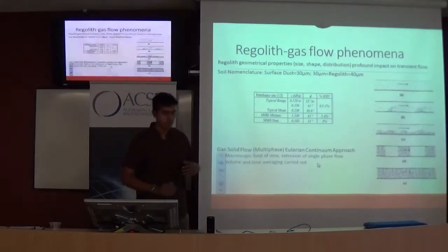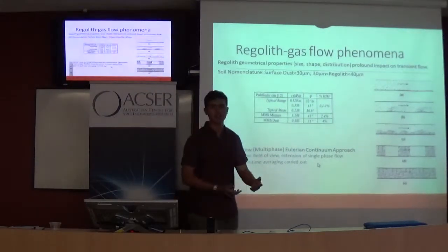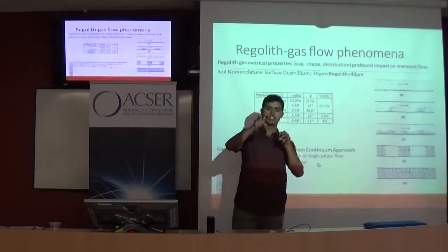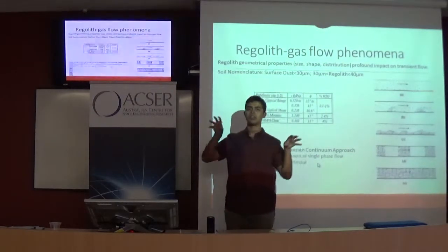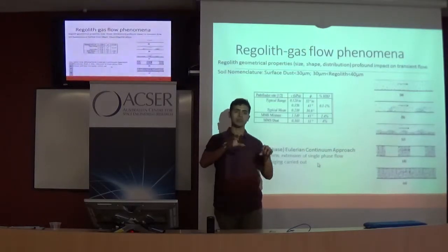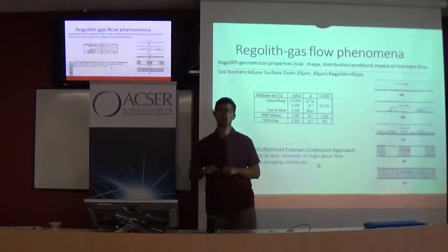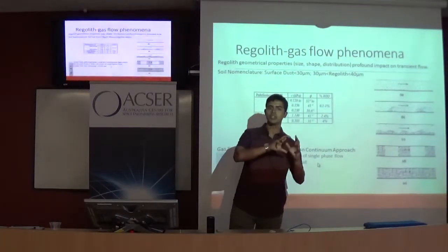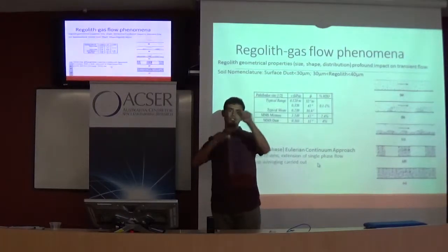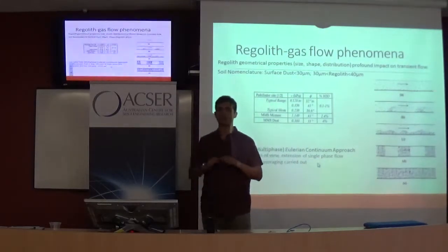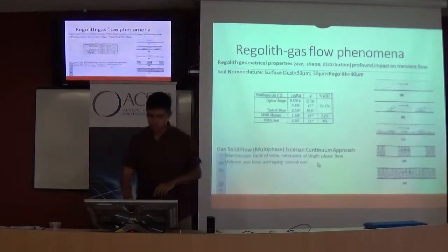There are different ways of looking at it. There's an Eulerian way of looking at it, and there's a Lagrangian way. By Eulerian way, you mean that you put certain pitot tubes all around in your zone, and each of those pitot tubes looks at the flow particles in its surroundings and tries to understand. And Lagrangian is when you're trying to send out particles and follow them, and you're trying to get an overall view of how each of those particles are behaving.